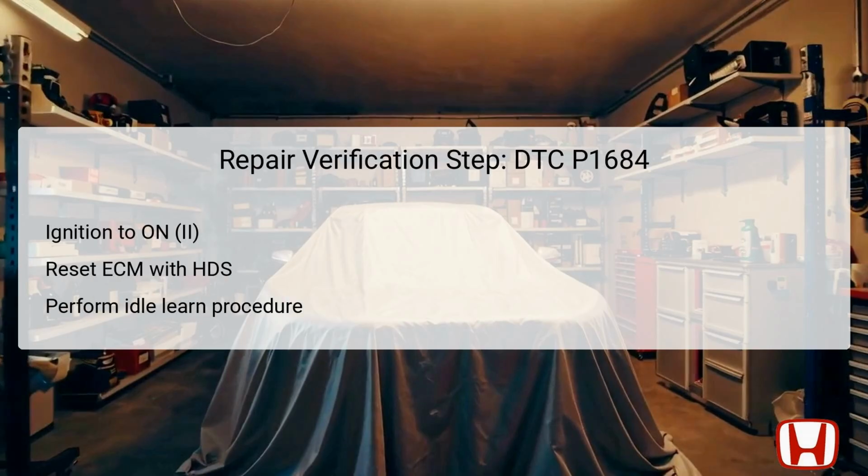To verify the repair after addressing the throttle body issue, begin by turning the ignition switch to on again. Use the Honda Diagnostic System, HDS, to reset the engine control module, ECM, ensuring that it clears any stored data that could interfere with engine performance assessment.